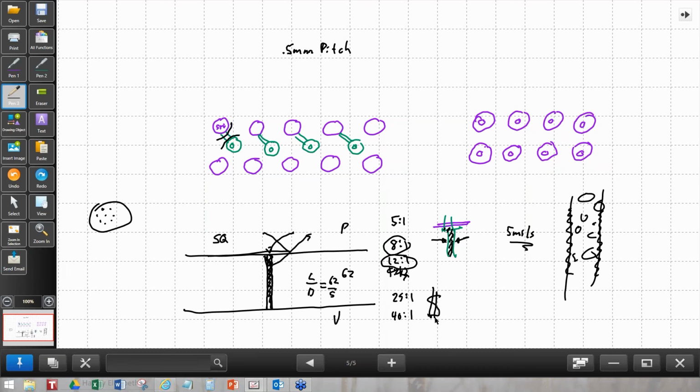But remember, they're still fragile, and they act like a small wire, so they may not electrically meet your needs. If you're going to do via and pad, you're still going to have your solder mask around the outside of these. You're going to have the holes drilled. Once the hole is drilled, it will typically have to be plugged, refinished, and plated over with copper, so that when you look at it, you see nothing but a flat pad, knowing that underneath there is a hole that's plated all the way through.